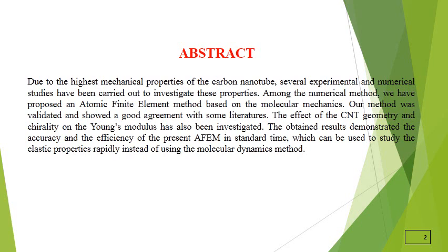In this work, we use a simple and suitable atomic finite element model capable of describing the different interactions between atoms and predicting the elastic properties of carbon nanotube. Also, the effect of carbon nanotube geometry on the Young's modulus is investigated. The obtained results showed that our method is fast and gives acceptable accuracy for predicting the elastic properties of carbon nanotube.